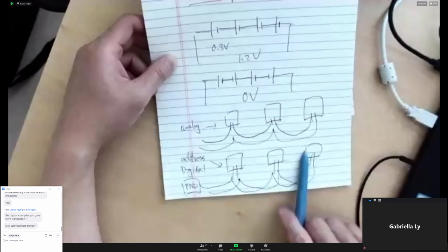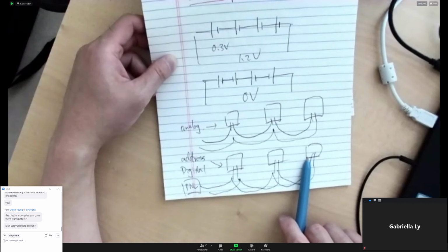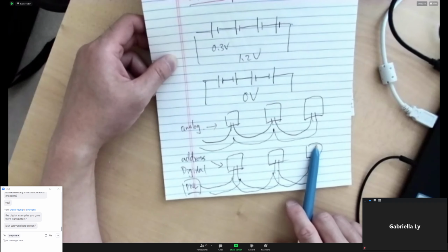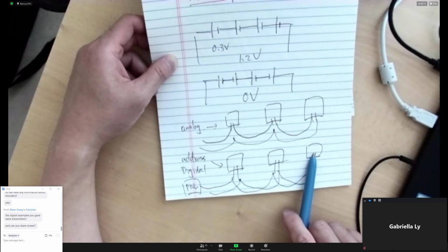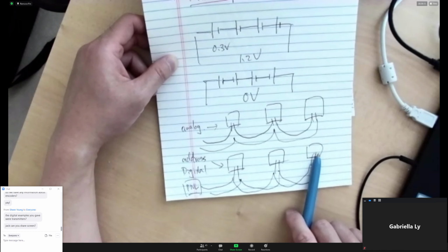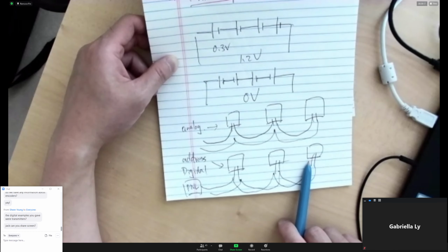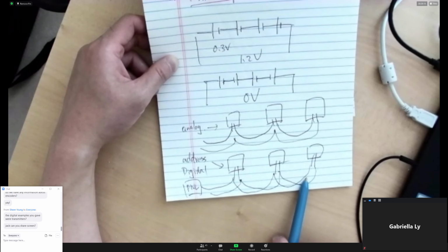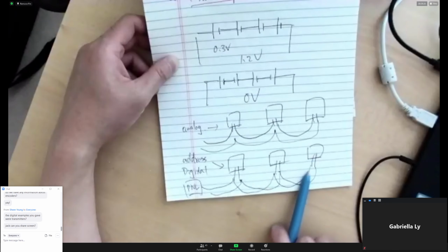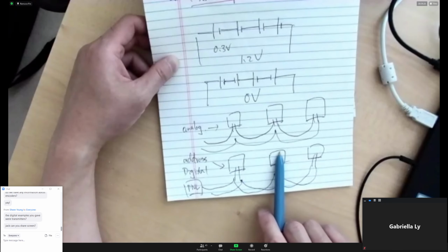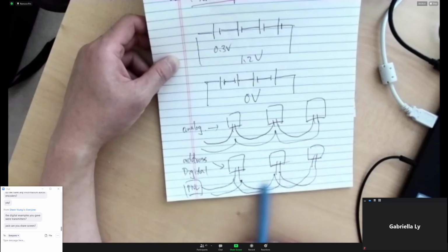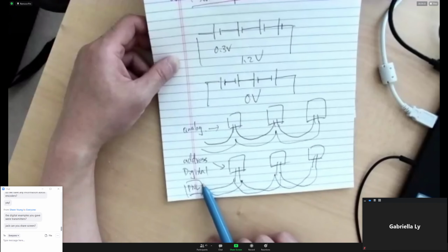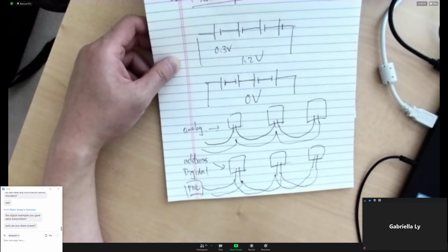And if something happens down there, if someone pulls the pull station or the smoke detector or heat detector gets activated, they will get on the bus. They will say, okay, I detect a fire alarm situation, I want to report to the panel. When they send that message out, every other device is going to be quiet, letting this device talk directly to the panel. So those are considered digital communication.